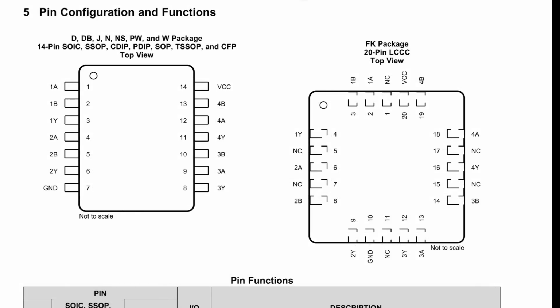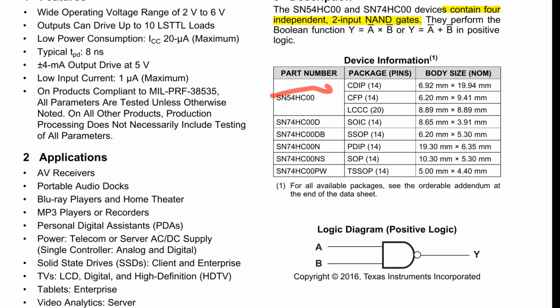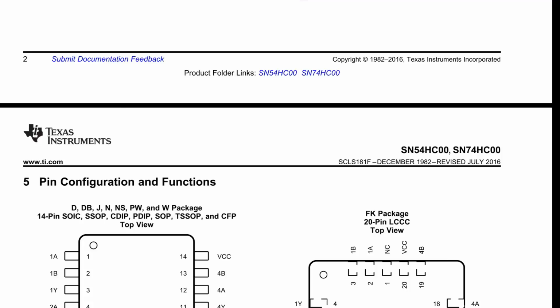And then we've got our typical pinouts here. These are for pretty much all of the packages. So for the SSOP, the SOIC surface mount ones, for the DIP, plastic DIP, the ceramic DIP packages. Oh, by the way, we didn't show up the top here that the 54HC, this is the military version, the 5400 series, and that has a ceramic DIP package version. It's just a more robust version than your regular plastic DIP package, because the military like their ceramic DIPs. So anyway, let's not get mixed up in that.